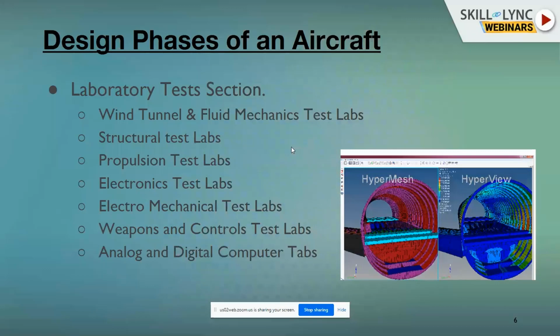So for each and every component, like if it's a composite, if I have different orientations of ply, 0, 45, minus 45, 90, and with a certain set of fasteners, I test each and every configuration of a laminate to get my allowables. So you need structural labs, you need internal labs. Then this structural test data is really important, because without allowables you cannot get the margin of safety, which is allowable over applied. Without that you won't get it, right?